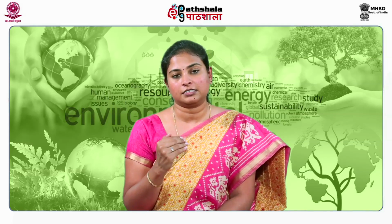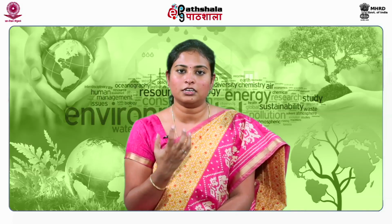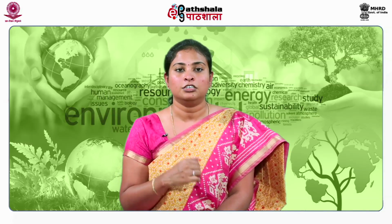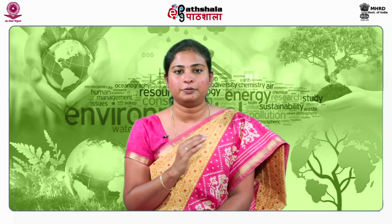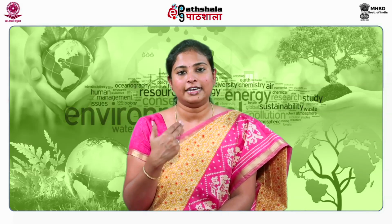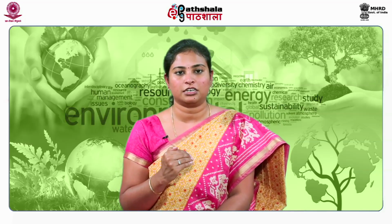So, leachate flux, the rate of leachate generation, is very important because this is going to be used as a source to maintain the moisture inside the landfill. So, leachate recirculation should be continuously monitored and the moisture levels within the bioreactor should be continuously maintained. Also, you should be careful to avoid excess moisture because it will reduce the degradation efficiency and gas production rate.